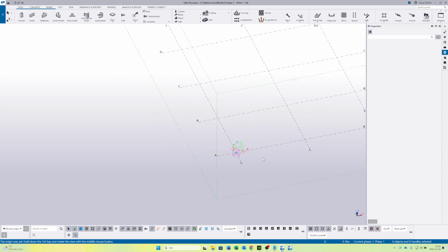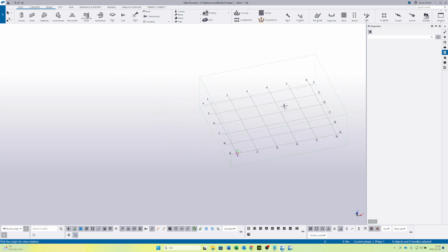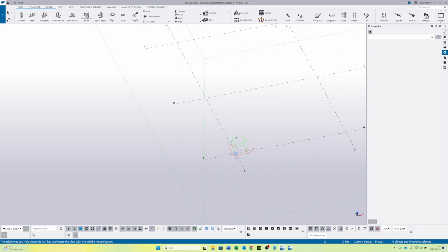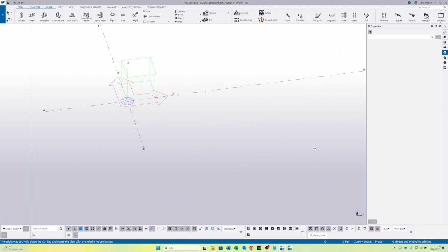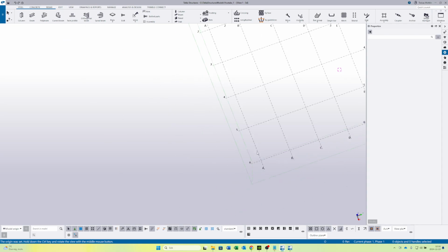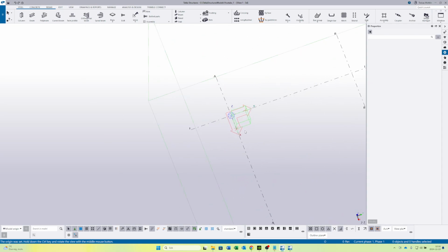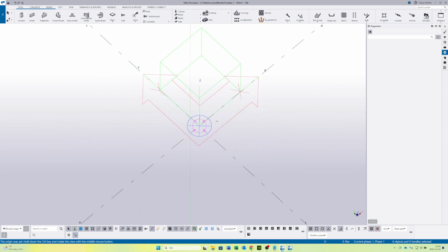So, and this is important because sometimes, let's say that you have this way over here and you're working on a column here. When I try to rotate now, you see I'm going to rotate away from my point and it's going to be all weird when I try to navigate. So a general tip is to just always have your rotation point where you are working. It makes it easier to just look around and see so everything is correct.